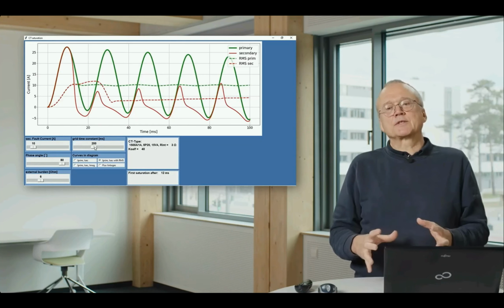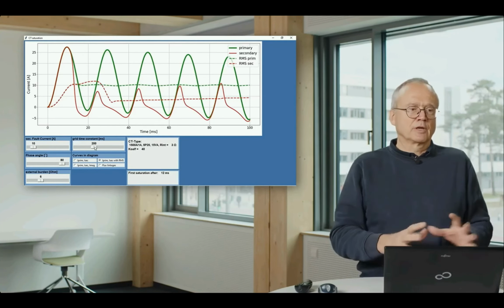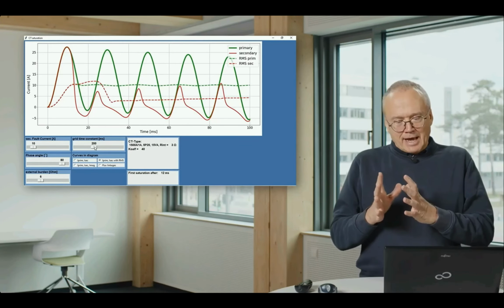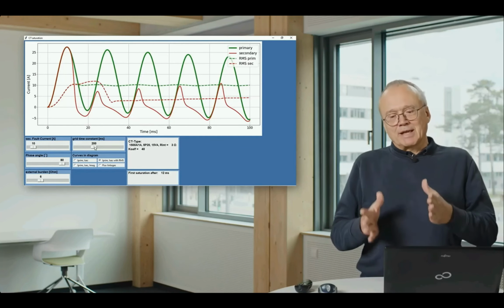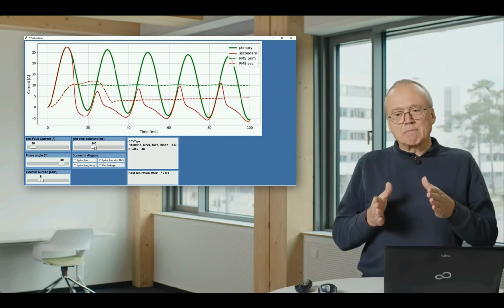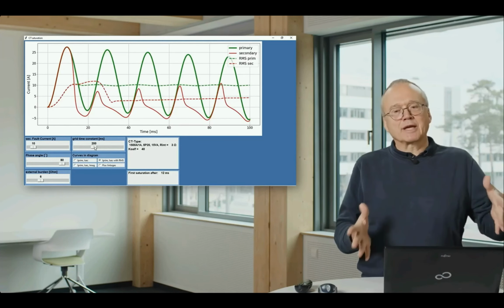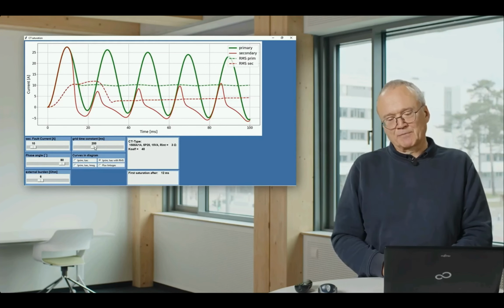If we are, for instance, inside a medium voltage cable system, away from transformers, just in the system, and then calculate the short circuit loop impedance, this is in these cases mainly defined by the impedance of the cables behind us, the cables which limit the short circuit current.